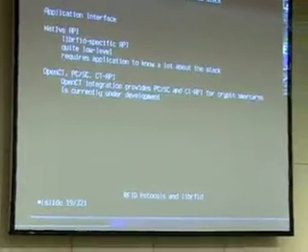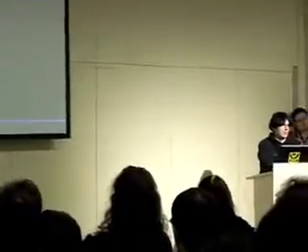There's currently only a fully supported native API, which is an API that is specific to LibRFID. You will not find it on any other RFID system. It's quite low level and requires lots of knowledge of the application about RFID, which it shouldn't need to know. I'm working on integrating with PCSC, CT API, and OpenCT, so you can use common APIs that are used for contact-based smart cards with contactless smart cards as well.